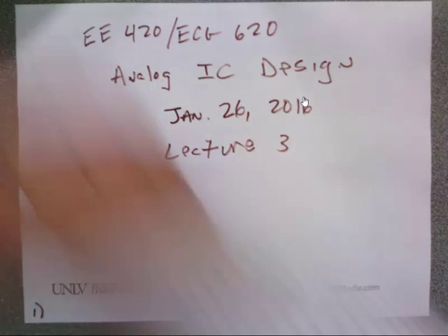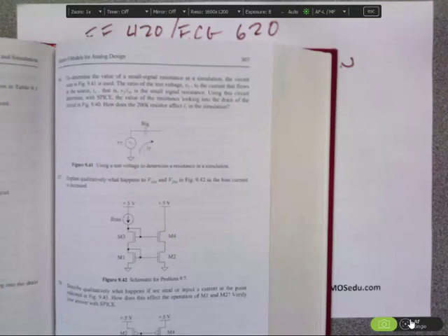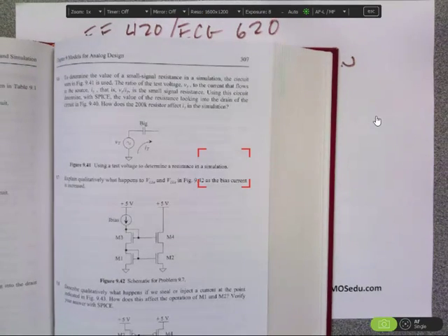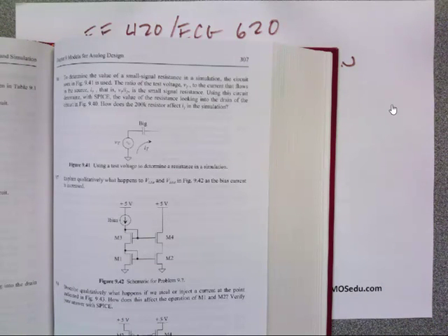Before I proceed, if you say big capacitor here and you put 1F, what did you do wrong? 1 farad's pretty big, right? But 1F in SPICE means 1 femto, or 10 to the minus 15. So if you did that, it ain't going to work, because you're not putting a big capacitor there, you're putting a teeny capacitor there.